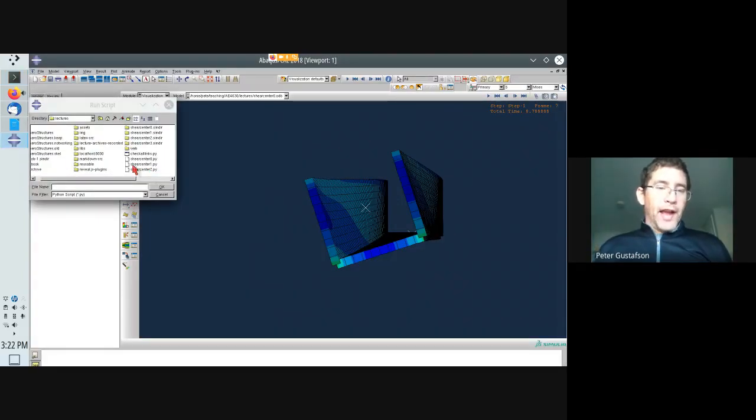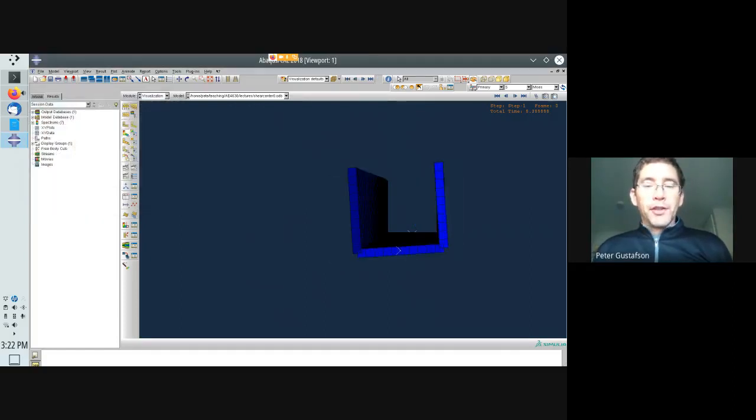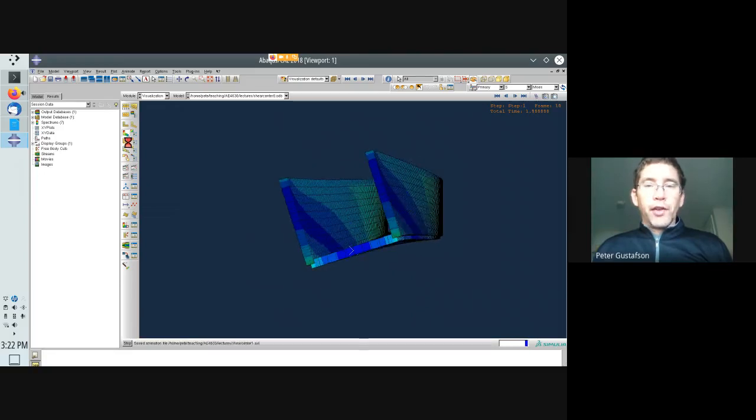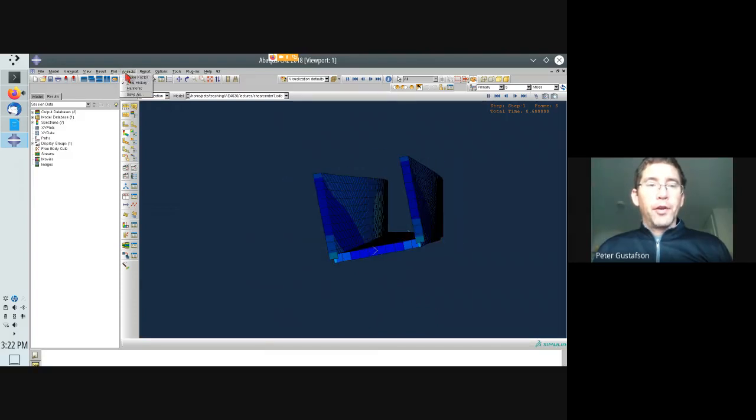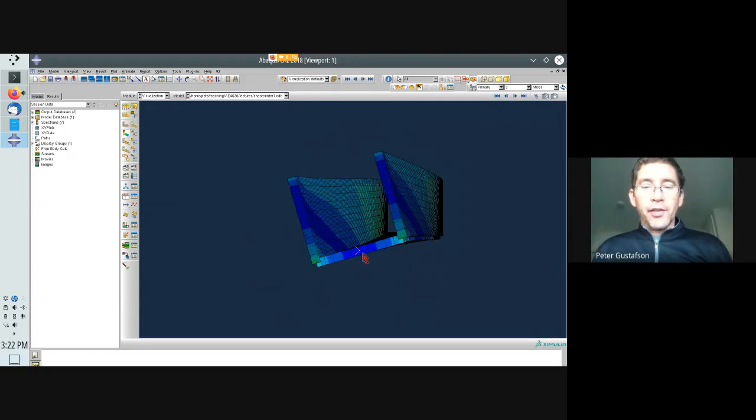I've actually done that in this case for 4 different models, where I've loaded the cross-section at different areas. The one that we had looked at so far, I called shear center 0. So this is essentially close to the centroid. Another area I might choose is this one. Now you can see the X in this model.